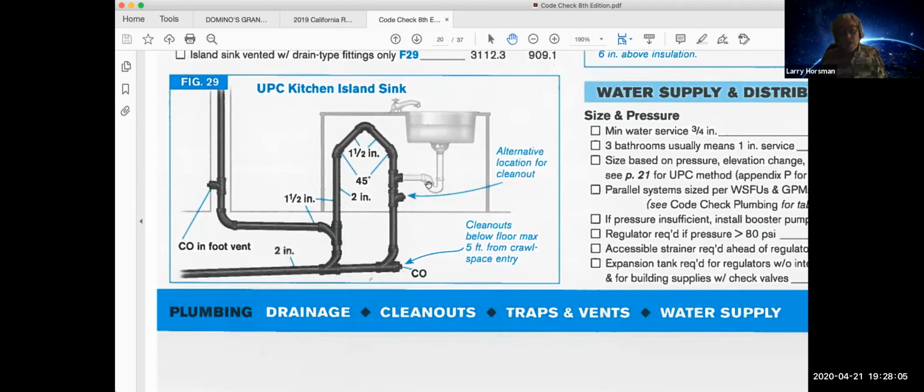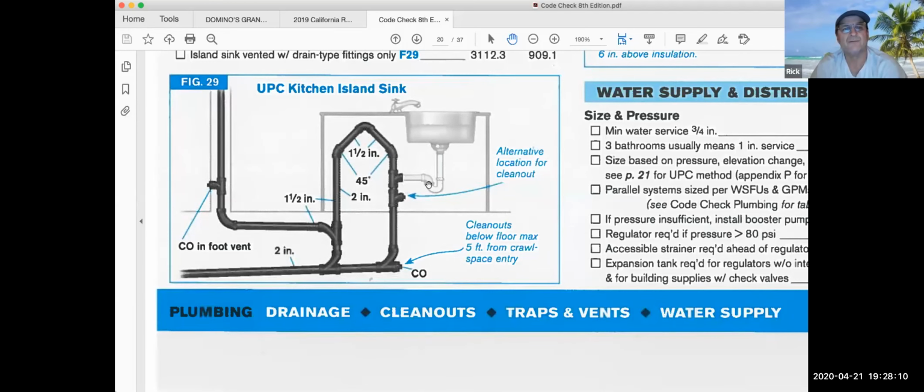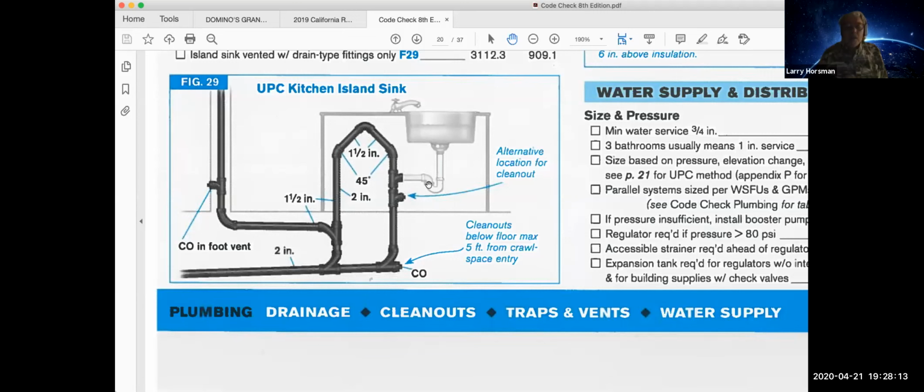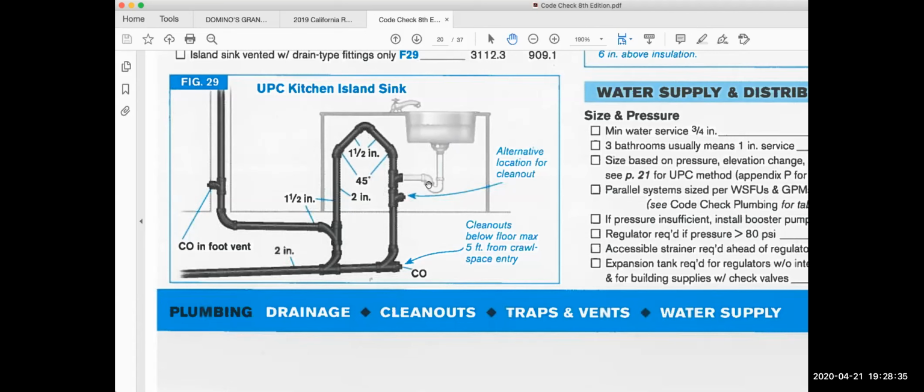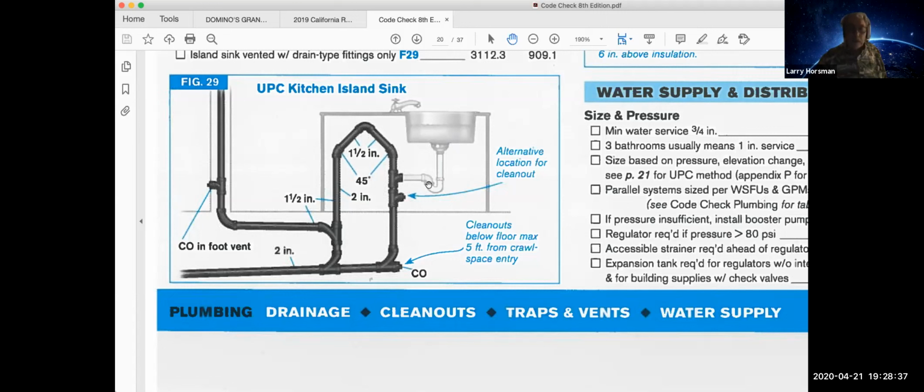If you let it sit there for a while, sometimes you'll notice it gets pretty stinky. Yeah. The water starts to smell bad, starts to smell like rotten eggs. And that's the hydrogen sulfide, which is soluble in water. And so you can run some water down there. You can throw a lemon down there or something similar to try and change it. But after a while, if you're not using it regularly, then it's going to get stinky. And that's just because those sewer gases are dissolving in the water. And some of that odor then is coming up from the trap.